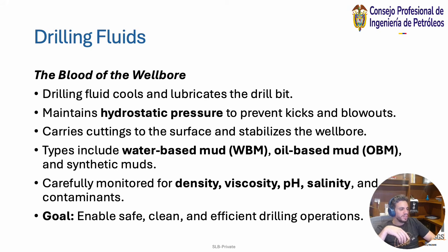So we need to circulate, the same way we clean, we must circulate fluids around the well to maintain this pressure. So we're manipulating the environment of the drilling through the use of fluids to maintain a hydrostatic pressure so that nothing like a kick or a blowout occurs, right?